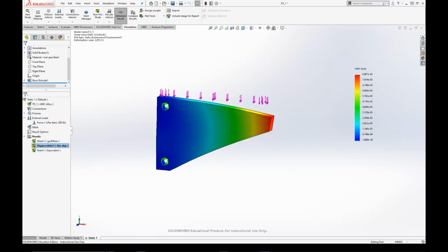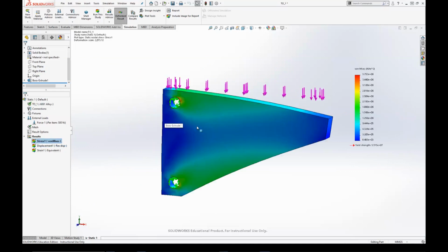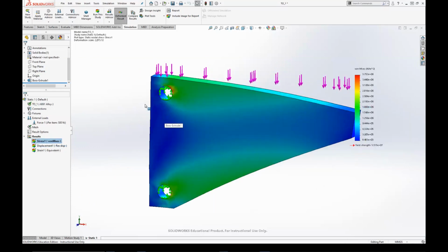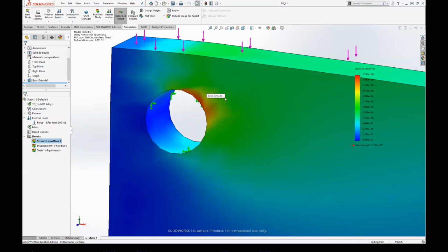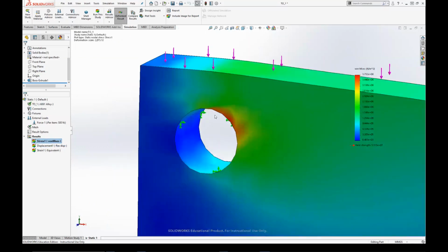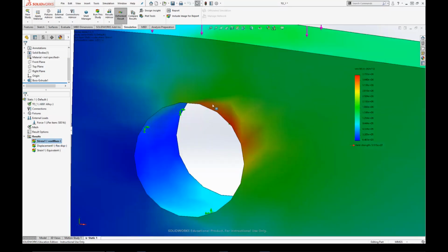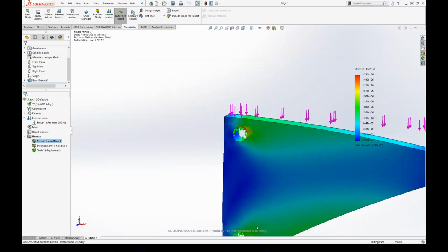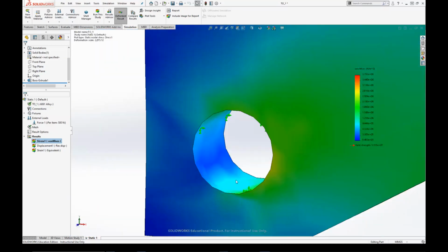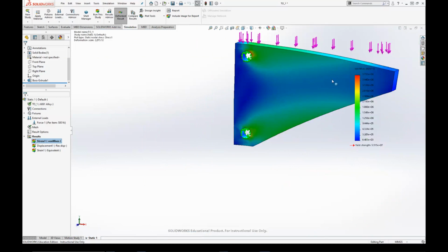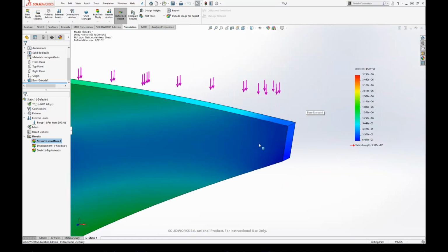Okay. So you can see the stress acting onto the body and the area where maximum stress is there. The part where it is being fixed is the area where maximum stress is there. And the part in the middle is where the minimum stresses are there. So now I got to know that my part is not failing under the load which I apply to that part.